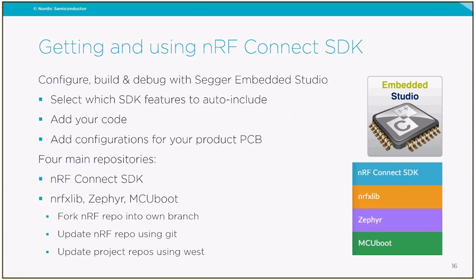And we haven't called our folder nRF Connect SDK, we have just called our folder nRF. But basically the nRF folder is where we have most of our application code. Yep, and then of course you have nrfxlib, Zephyr, MCUboot. You basically fork the nRF repository into its own branch, and then you update the nRF repository using Git. The project repositories are then updated using the West tool.